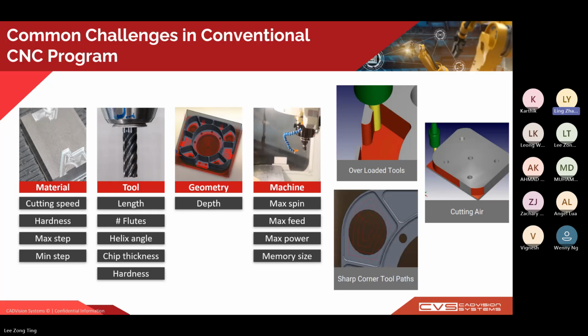So this often results in a slower overall process and inefficient use of the cutter, since only a small portion of the tool cutting edge is engaged most of the time. And this not only hurts your productivity, it also shortens your tool life, increases your machining costs, increases your machining time, and limits your ability to scale.